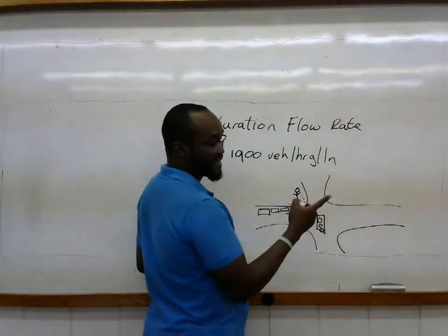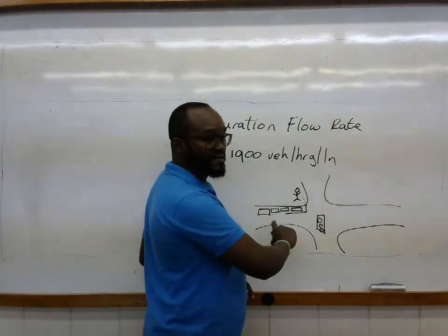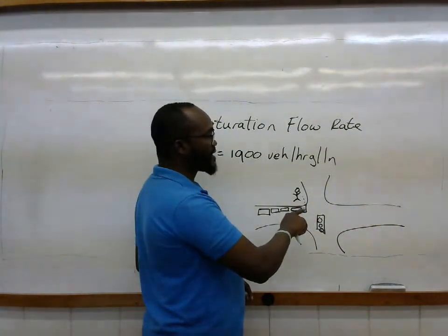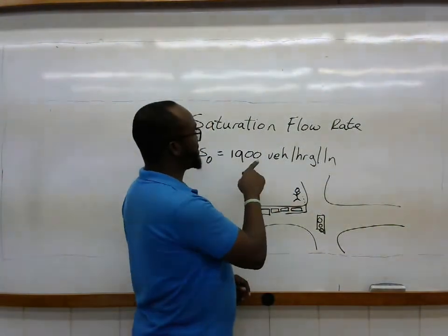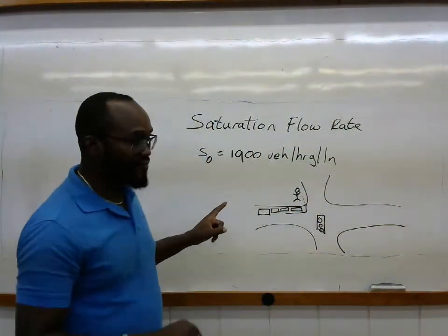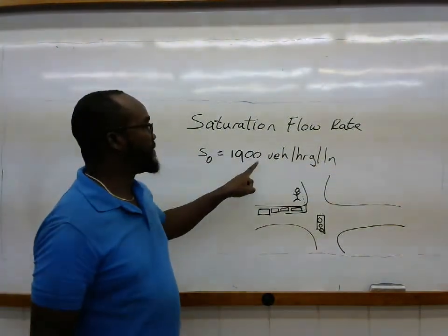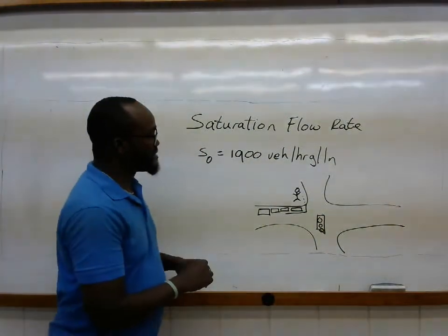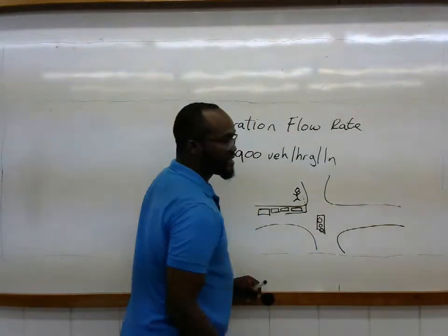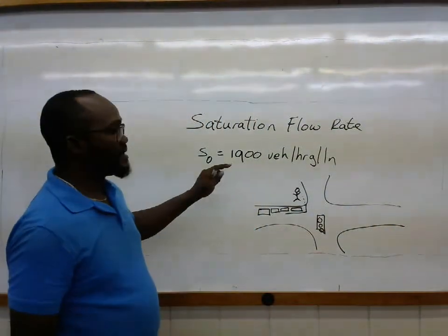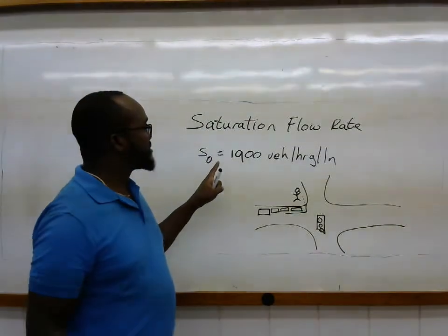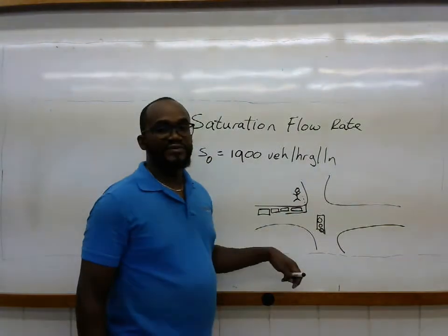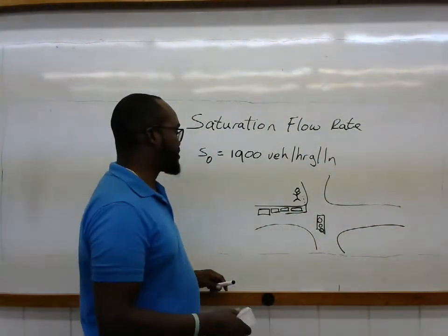Okay? So, just as the definition mentioned, it is the maximum number of vehicles that can go through the intersection in a particular direction, assuming 1 hour of continuous green. So the units of the theoretical saturation flow are vehicles per hour green per lane. Okay, so why is that important? Well, in terms of determining capacity, we need to, if I may use the term, calibrate this term to better understand what the available capacity is through the intersection, along with the other terms that we mentioned before.